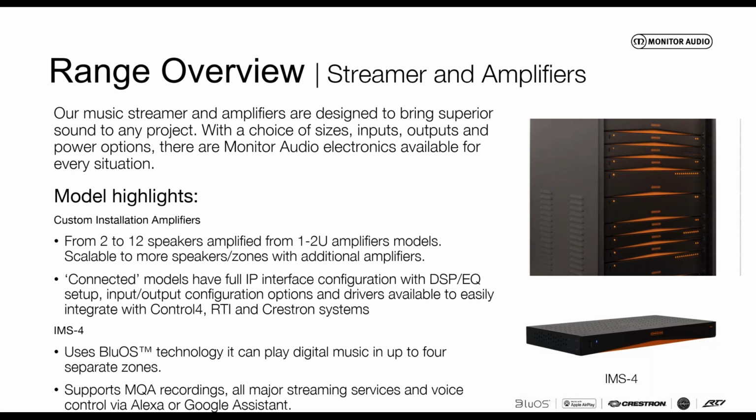You can daisy chain these models up. Some of the models feature a bus, so you could feed a source component in and feed out to multiple zones and multiple power amplifiers. There are also multiple switching options on the amplifiers: you can get it to auto sense on audio inputs, or switch on via a voltage trigger, or, up to the connected models, which are the units that feature an Ethernet connection. They have a full configuration interface which you can access through an IP address, and that allows you to customize those units to your heart's content.